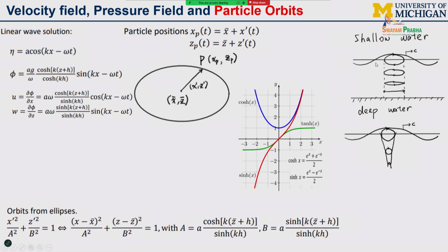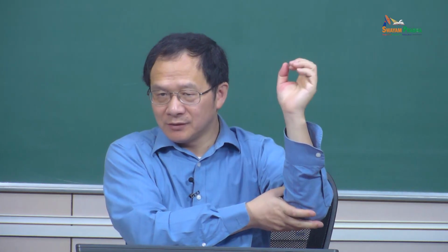However, in the shallow water it is different. In shallow water you still have the horizontal dimension. So look at this one. If you design some wave energy converter, right, for the shallow water to work, you probably want to make use of horizontal motion. For example, you have a surge wave device, right? Take advantage of this surge motion, because the surge motion amplitude doesn't decrease, right?